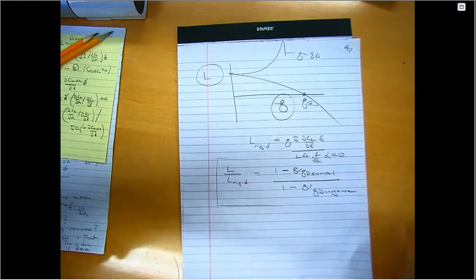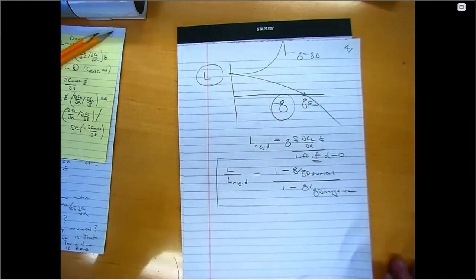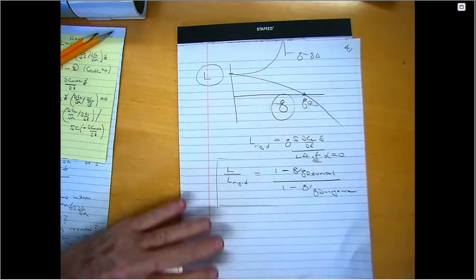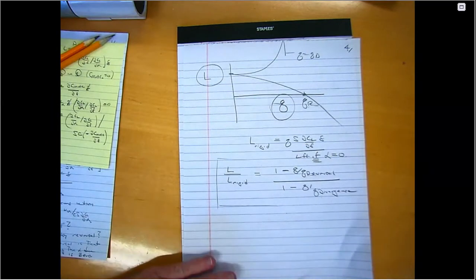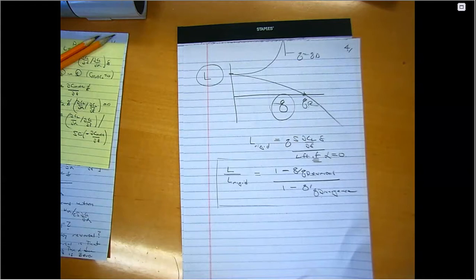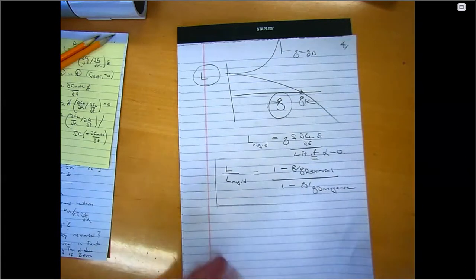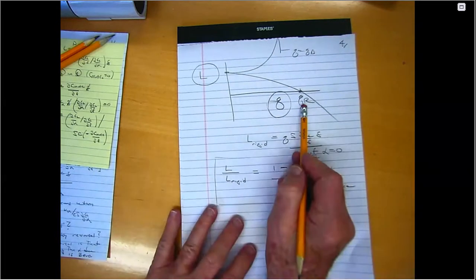And the reason it's down is because the twist itself has changed, right? When I rotate the control surface down, the twist actually goes down. The twist due to alpha is offsetting the twist due to delta. And there's a certain condition in which those two exactly balance, and that's the reversal condition.